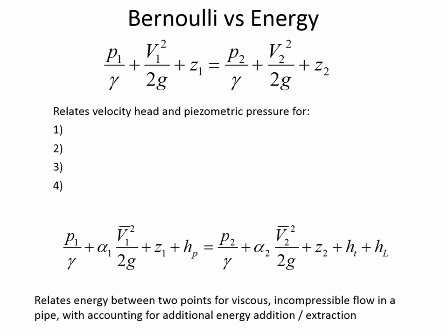Well, it will add the same amount of energy. The thing you need to keep track of when you're having a pump, you mean a pump, right? Not a turbine. If you are having a pump, then you remember we talked about cavitation? You want to have the pump before the pressure of the water goes below the vapor pressure. So as long as you're avoiding cavitation, it doesn't matter if it's early or late, it adds the same amount of energy. It's just where you add the energy is dictated by avoiding cavitation.